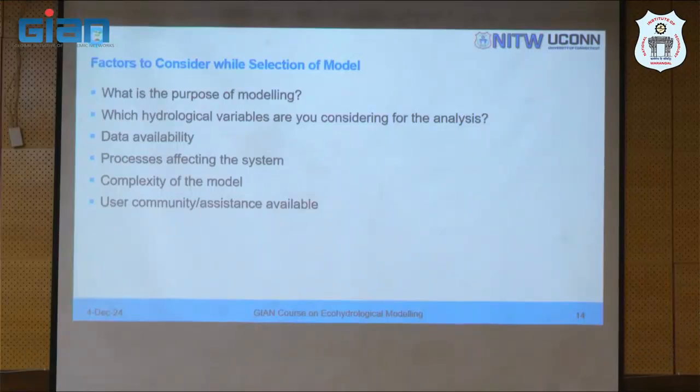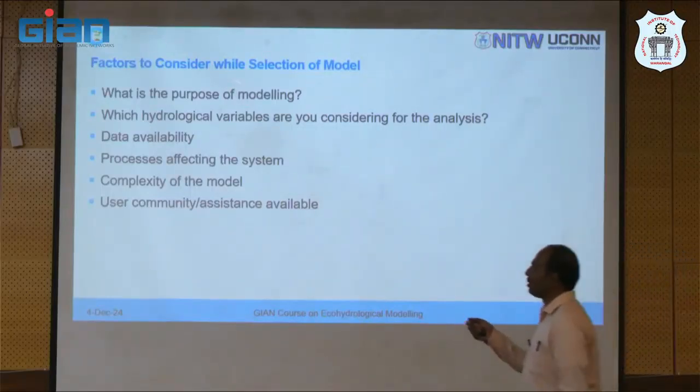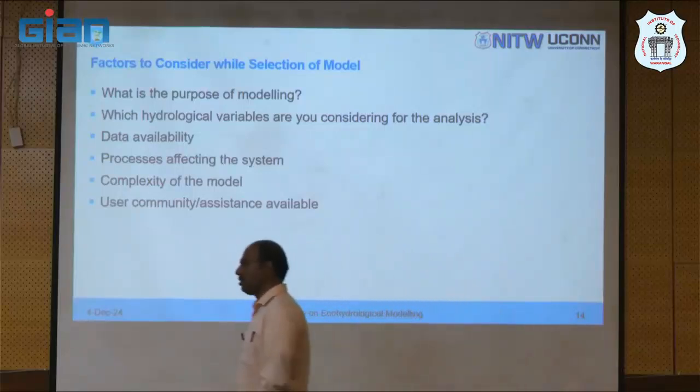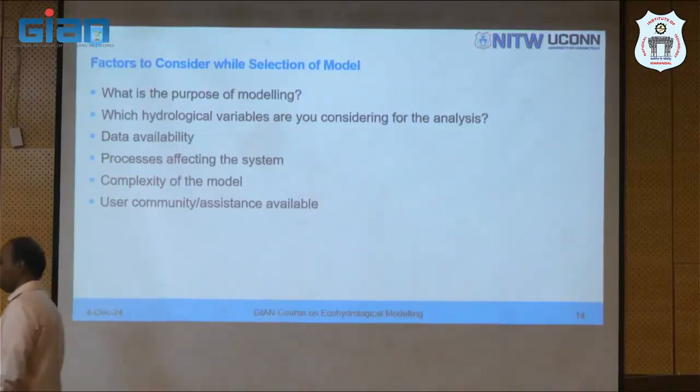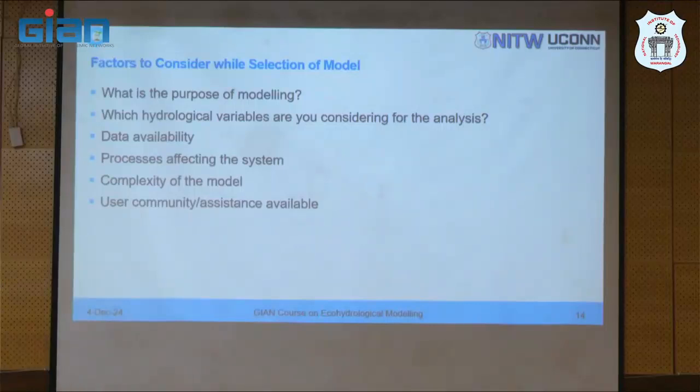Now, which hydrological variables are you considering for the analysis? Are you considering stream flow? Are you considering ET? Are you considering groundwater recharge? Are you considering base flow? Depending upon that, you need to choose the model. Now, these two are the primary drivers of what model to choose. But even with these two, there are still n number of models available to you.